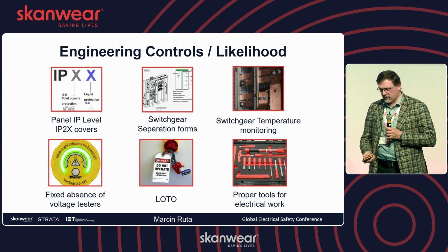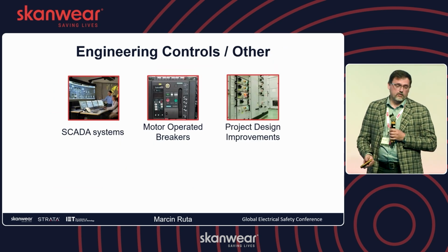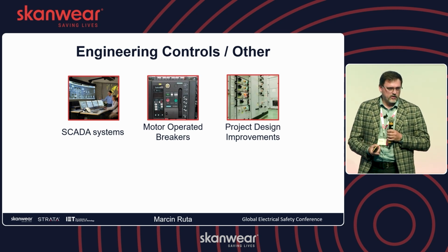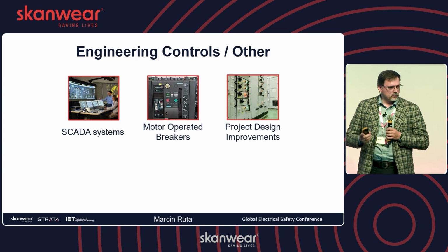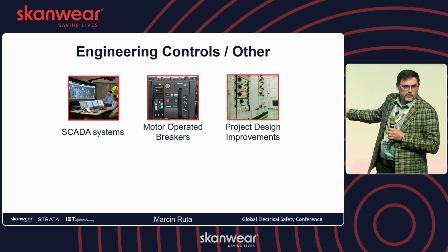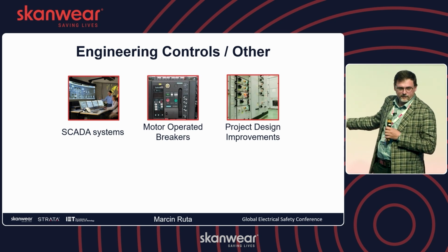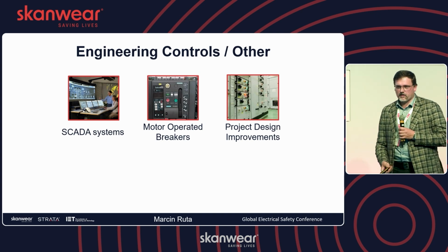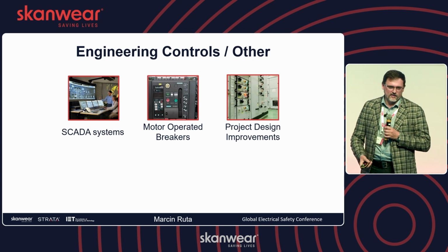Proper tools I can skip as a good example, and also things which are kind of mixed. SCADA system for remote operation. I can tell you where it doesn't work. It doesn't work where you put the panel operator next to the breaker. Then it's very bad design. I would say you can sometimes design things as new, but unsafe by design.